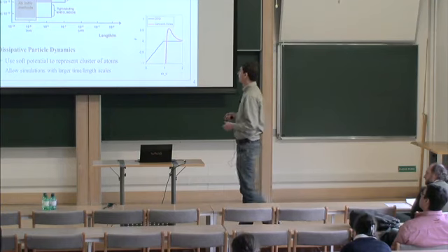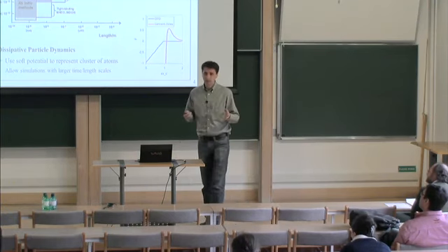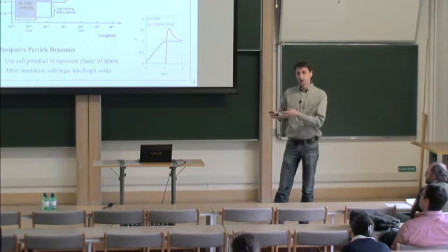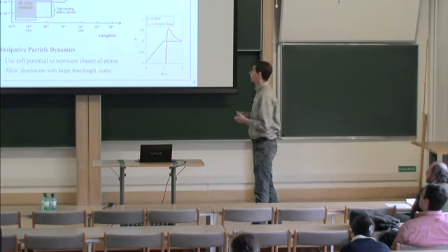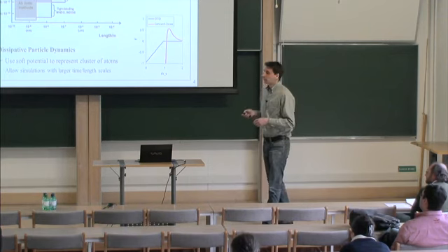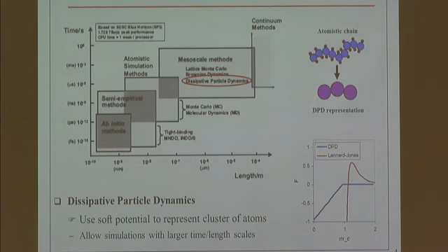We use dissipative particle dynamics, which is a particle-based method. Essentially, you can think about it as coarse-grained molecular dynamics. So we have particles that interact, and there are two ways we coarse-grain these particles. First, each DPD bead represents a bunch of molecules, right? Or even maybe better to say it's representing some small volume of fluid, right? And then this volume of fluid, a bunch of the molecules, they interact between each other.